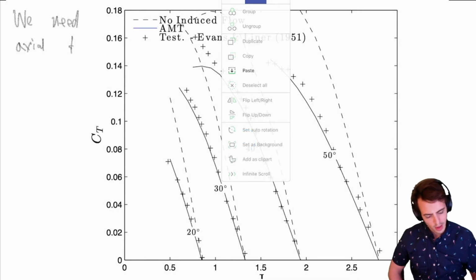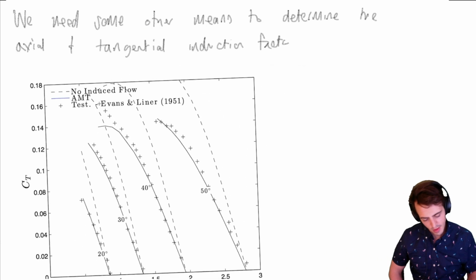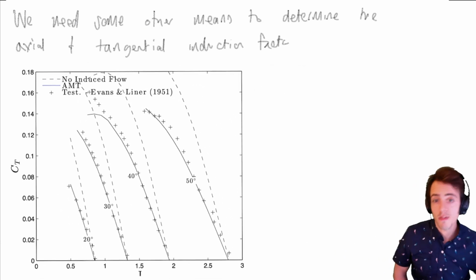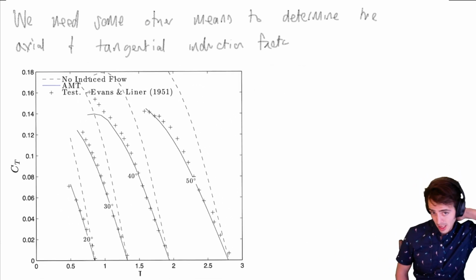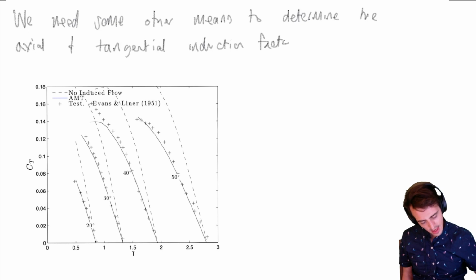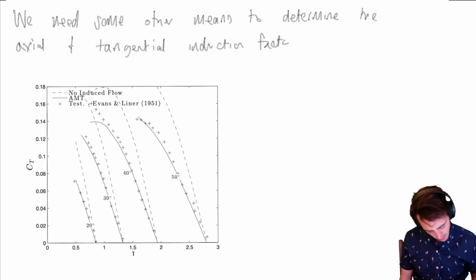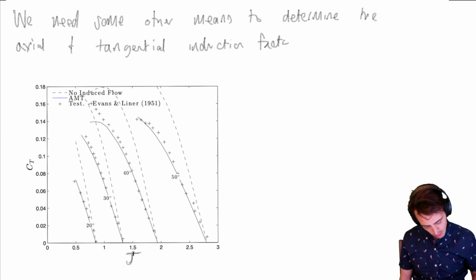So I've also included in the papers repository a link to my dissertation where some of these are included. Be mindful that there's parts of my dissertation that we're actually going to say isn't correct as we do this course. But this particularly here is looking at the thrust coefficient versus, I've managed to not cut this off the bottom, probably that's the advance ratio there. So remember J is V on ND.